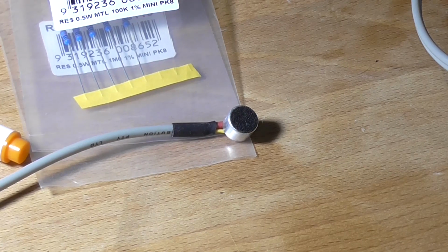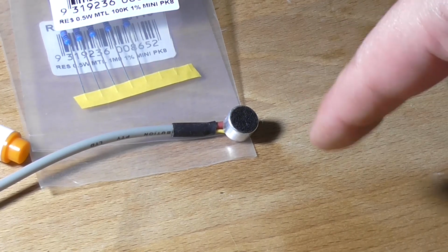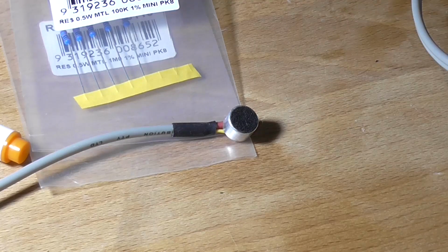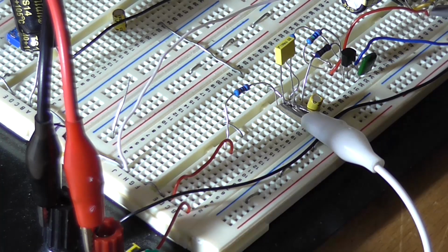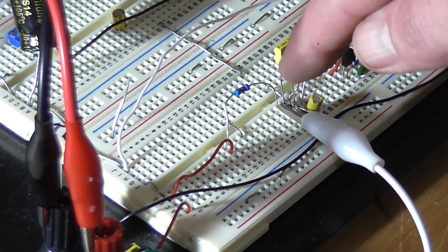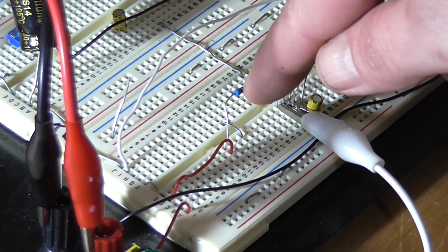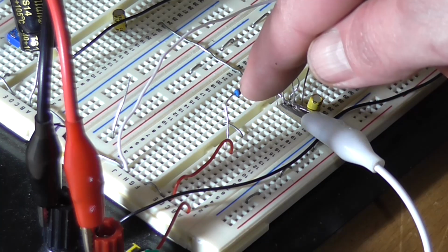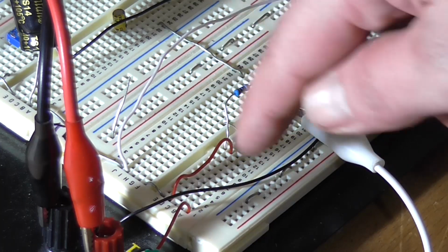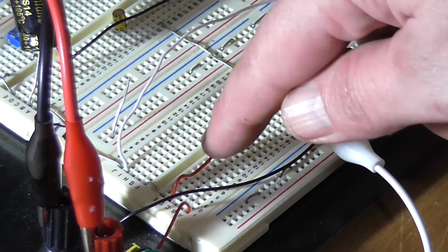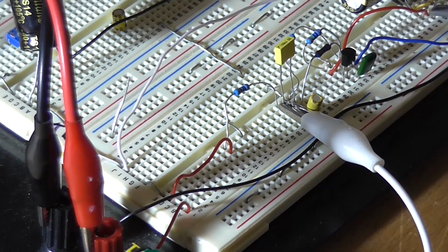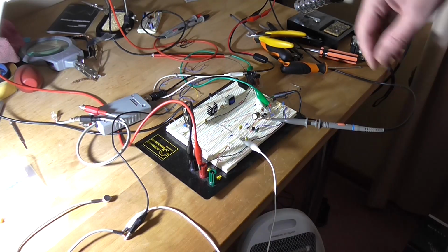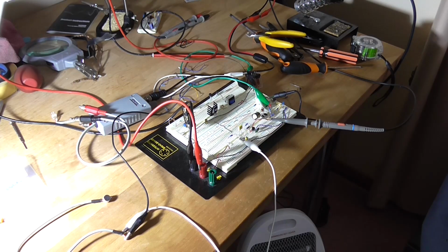So I've got a microphone insert here, an electret microphone, you know, standard one. That's connected to the circuit from the ground and the hot lead going into the capacitor. Got a 22K resistor going from that same connection, which is the positive of the electret microphone, going to the positive of the circuit to give the microphone a bias voltage, otherwise the microphone won't work. So I'm going to be very quiet and turn the circuit on.